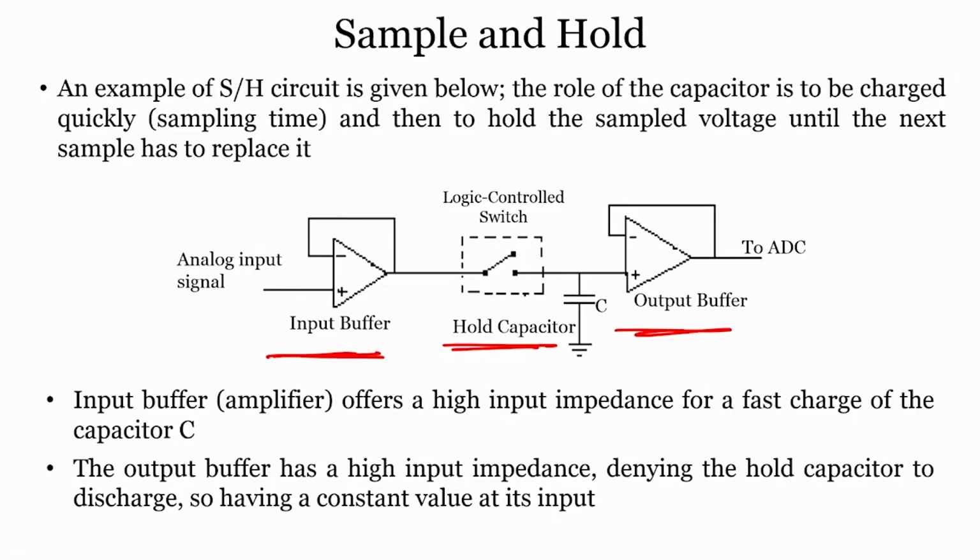And this is how the parameters for the ADC will work. To understand how the ADC works, you have to go through these parameters: understand how the coding works, how the sampling works, how the quantization effect works, how the sample and hold circuit works, and what the Nyquist theorem is, what the Nyquist rate is, and why Fs should be greater than 2 times Fmax. If you do not adhere to that, what kind of signal changes occur. This is what is given right over here.